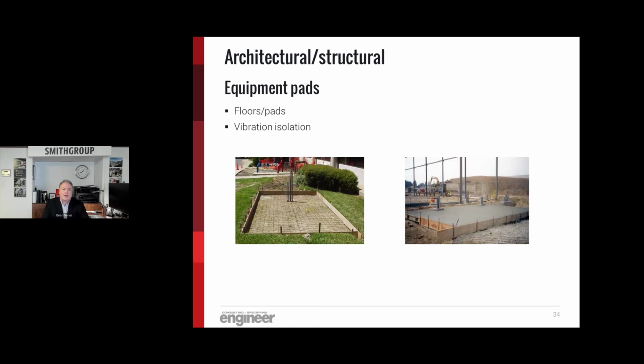Structural, you have to coordinate with structural, whether it's indoor or outdoor. You have to give them the weights, the vibration criteria, the movement. You have to look at the floor and pad construction, vibration isolation, particularly if they're located in buildings where vibration may be a concern to sensitive equipment outside the room.